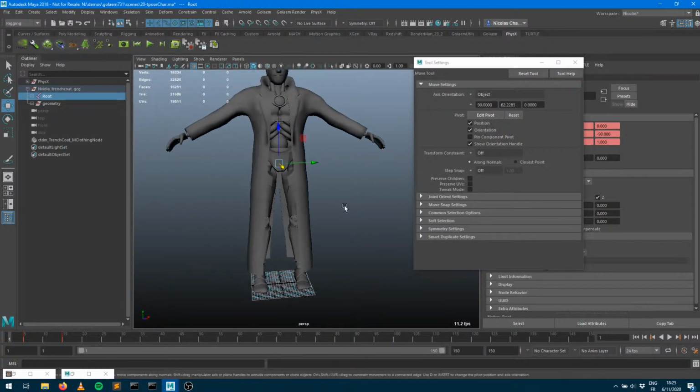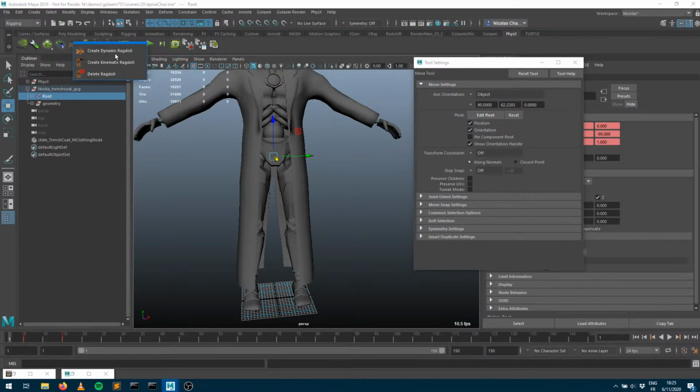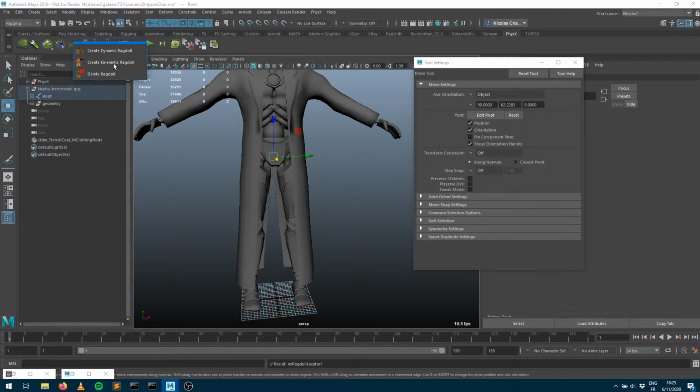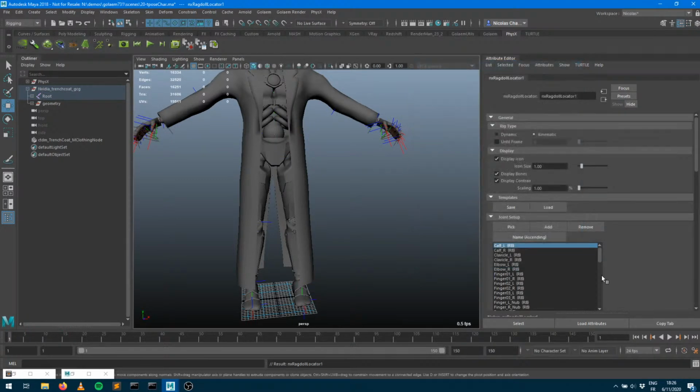And what I want to do is define some collision volumes for that character. So I'm going to select the root bone here, and I'm going to ask to create a kinematic ragdoll. It's really similar to what you've been doing within Golaem the rest of the time, where you assign a shape to every single bone. Keep in mind that it's just a limitation from the NVIDIA system, but each bone, each mesh, each cloth can collide with a maximum of 32 bones. It's written in the documentation, but just a quick word about that.